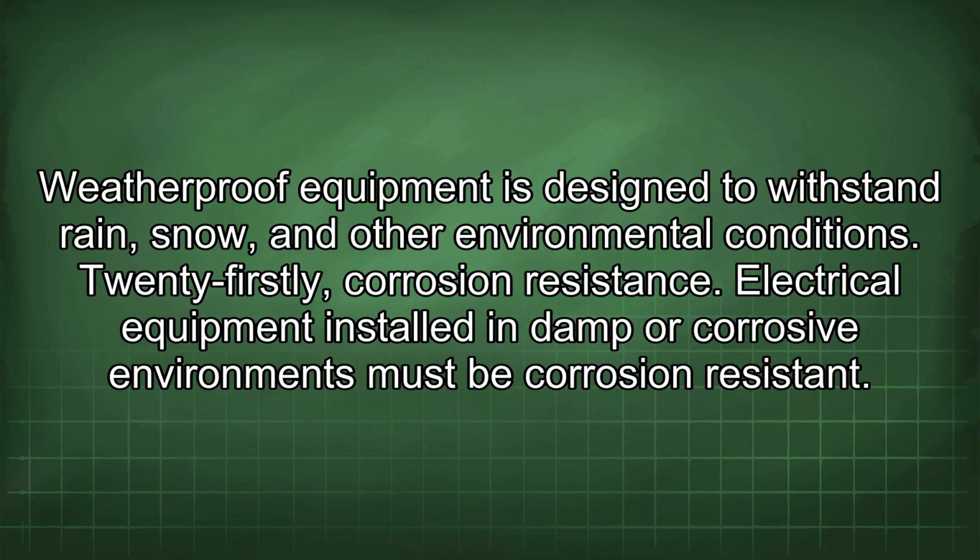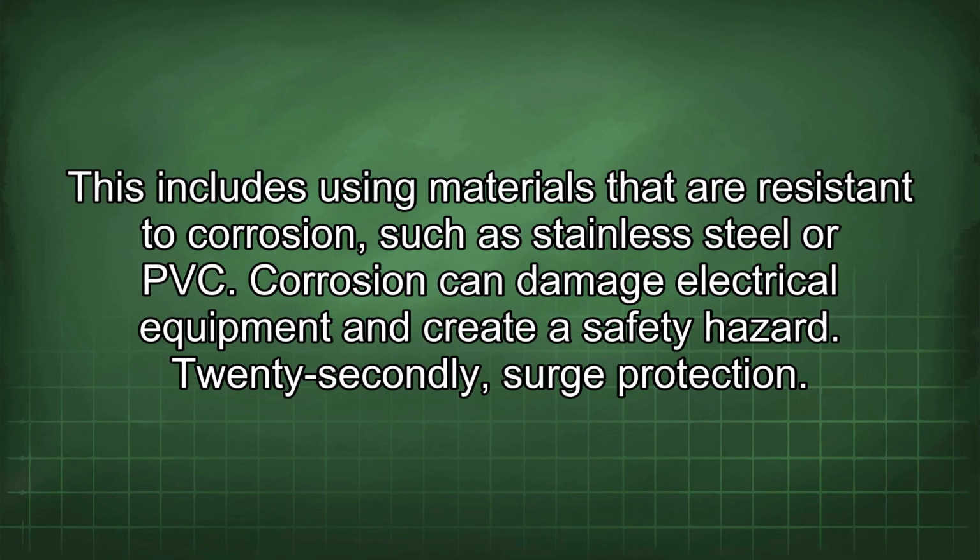21st, corrosion resistance. Electrical equipment installed in damp or corrosive environments must be corrosion resistant. This includes using materials that are resistant to corrosion, such as stainless steel or PVC. Corrosion can damage electrical equipment and create a safety hazard.